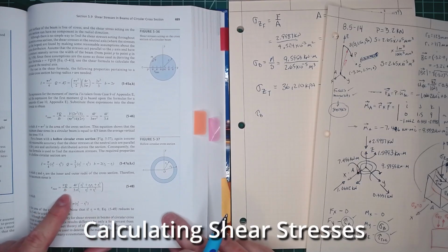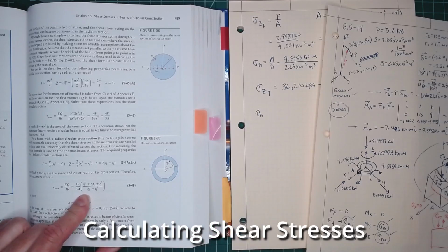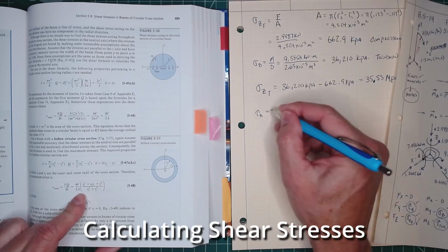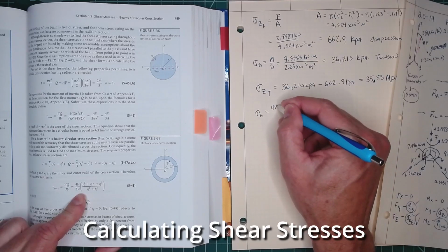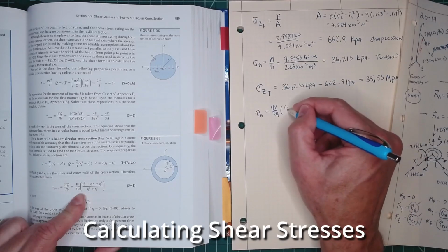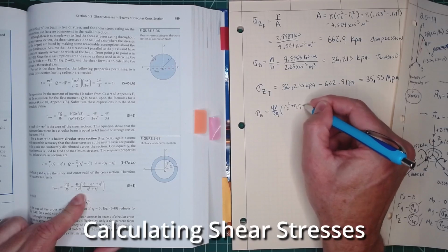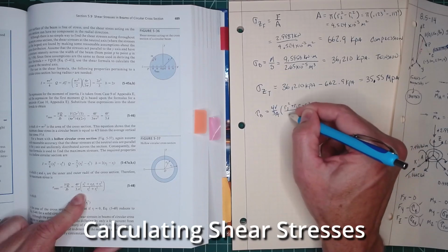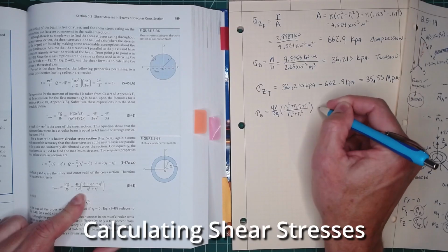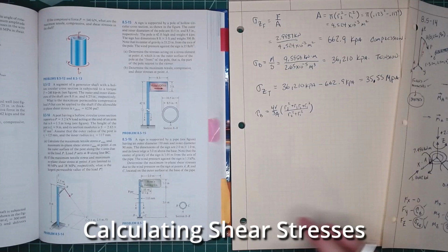We use VQ over Ib, or in this case for a hollow circular cross section, we can use this equation: tau = 4V over 3A times (R2 squared plus R2R1 plus R1 squared) over (R2 squared plus R1 squared). So we can plug all of those values in to get this shear stress.